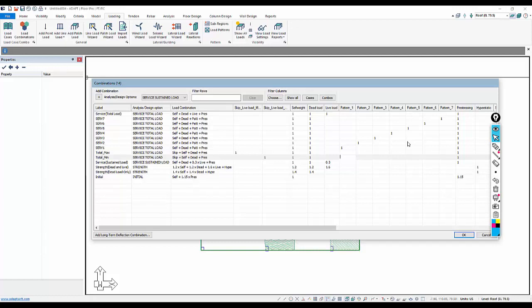Now, it may not make sense to actually set up both entries. In other words, if we already have to include these patterns for example, for deflection, we may not have to include these. The only reason you would want to include these is because if you look at contour deflections, you would actually have to go through and look at each individual result based on the pattern, whereas if you use the skip max min, you only have to see that once or twice for minimum and maximum.